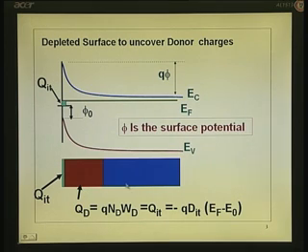Now, you can see for a given doping concentration what will happen. As D_it goes up, for a given Q N_d W_d, E_f minus E_0 will become smaller. I am keeping this constant, though it is not a constant, it is slightly varying, just as an example.